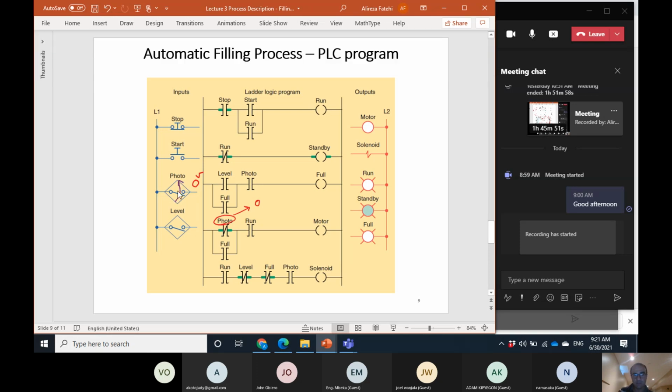So it closes when there's a box under the hopper. Then we have 24 volt here. As a result, the logic of this will be 1. And since this is normally closed, the logic of this will be 0. This means that the motor turns off. Okay, that's fine, because we want to stop the motor, the box, so the motor should turn off.